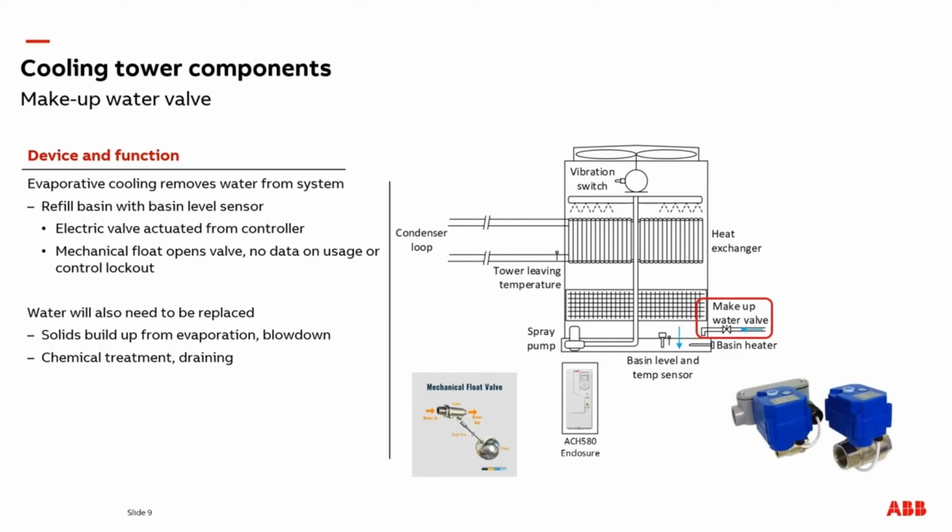Solids also build up in the tower basin over time from sediments in the water after evaporation, known as blowdown. These will need to be periodically drained and replaced with fresh or treated water.